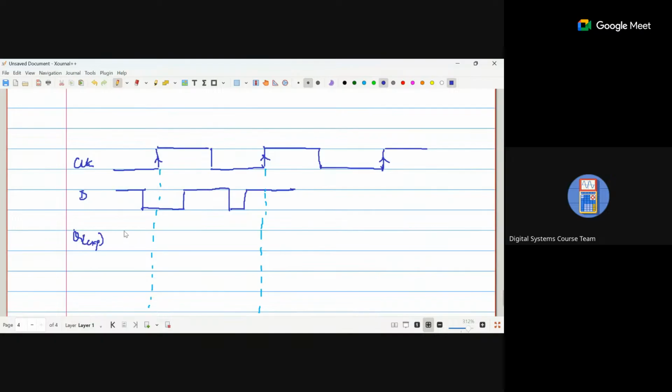So what happens till positive edge? Nothing, don't care, right? So you have a don't care condition there. And after the don't care condition, what happens? You will get whatever you get for D. Your D is here. So you got your don't care. After that, you got your D. Here, D. And what happens? It is a flip flop, right? So how does a flip flop work?